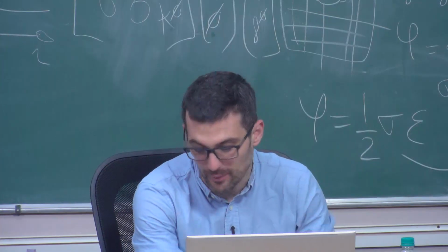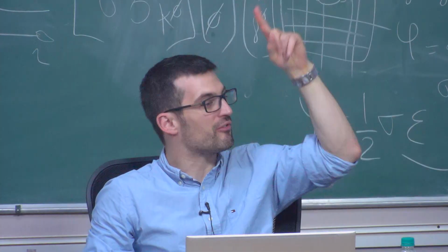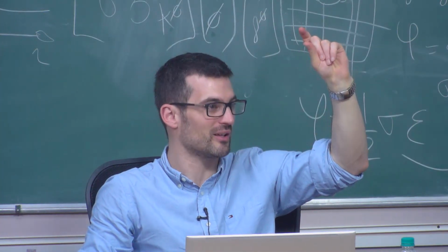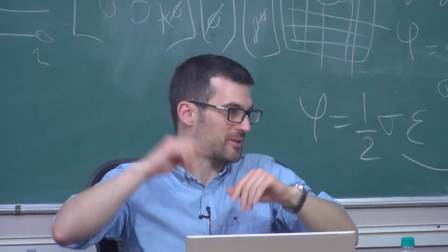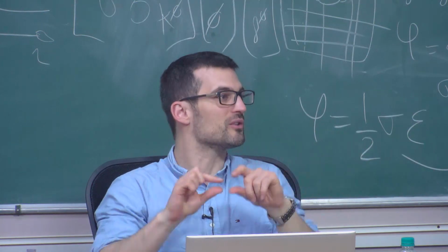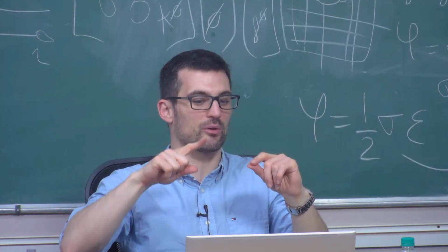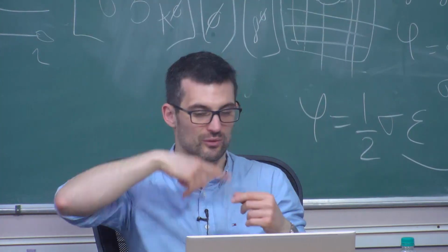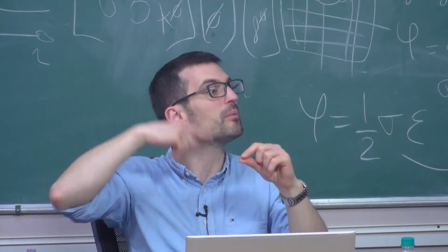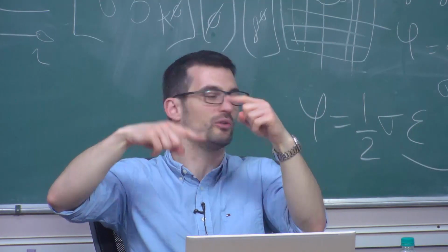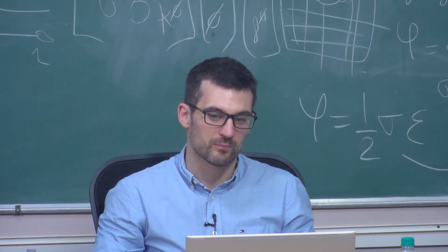There were several of them. For example, someone asked me, how do you implement the history field in the phase field UMAT code that you saw in Abaqus? There was no history field, right? I eliminated that line of code. It's on our website, but I eliminated it just to make it easier for people to see the simplest code. This extra line uses the fact that Abaqus allows you, in the UMAT, to have state variables, which are variables that you can keep and accumulate and call. So you store in that state variable the strength and the density of the previous increment, and then you compare. You take the maximum of the two, and that continues along. So just one line of code, for example. There are multiple options like this.